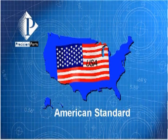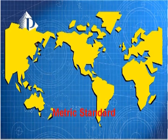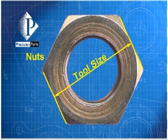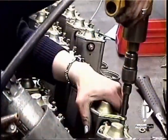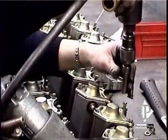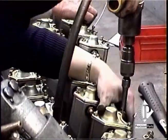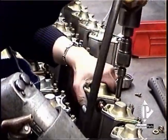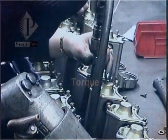PPR stocks sockets in both American and metric sizes. The proper size socket is determined by the measurement across the flat sides of the nut or bolt. Make very certain you are using metric sockets for metric nuts. Failure to do so can result in damaged product and tooling. Contact your lead or supervisor if you have questions about what size socket to use.